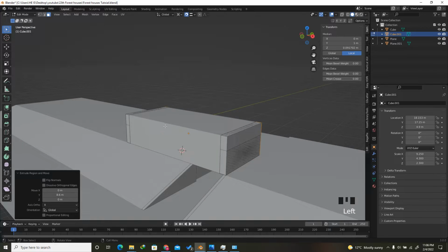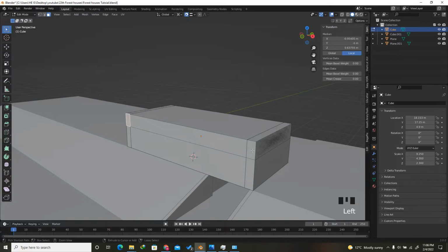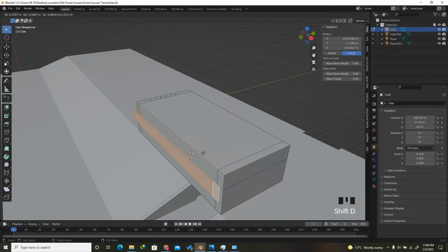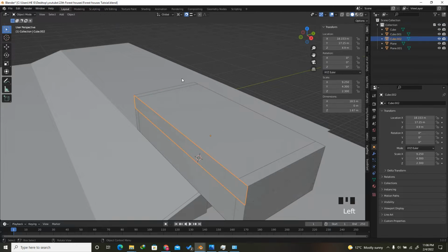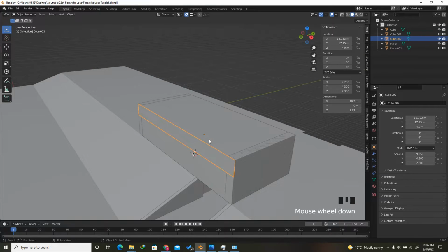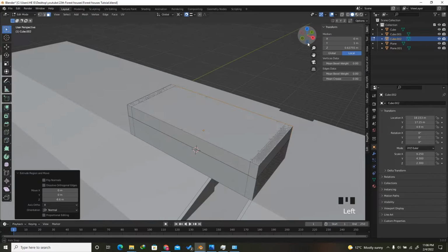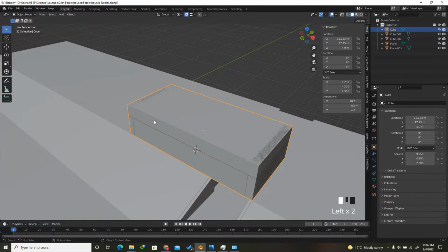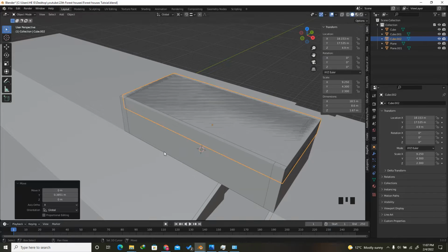After this, I'm going to get out of the edit mode and select this and get inside again. And I'm going to select this, hold Shift, select multiple faces and then press Shift D. It will be duplicated, and then P and then selection. It will be a separate object. So after this, go to the edit mode by pressing Tab and then press A and then E. It will snap right here since the snap button is activated. So after this, I'm going to select this one, let me deactivate the snap button, press G Y and move it a little bit on the Y axis.